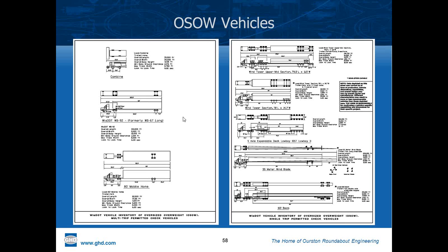And then those routes that were in the AB class where roundabouts might be located, a fleet of vehicles was identified that are probable and at times likely, if it's wind turbines and wind farms under construction. So the farm vehicle, pretty likely in rural Wisconsin, what's called the WB67 long, or has about an 80-foot trailer combination, and these are still on the road system, though they require permits.